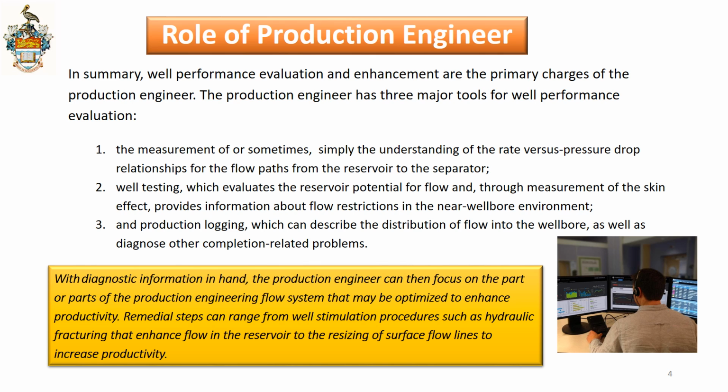Well testing evaluates the reservoir performance and also how the well is actually delivering the fluids from the bottom of the well to the surface, through basic well testing, which is routing a well to the test separator and measuring the rate and the flowing bottom hole pressure. Another technique would be production logging, running PLTs to determine what contribution is coming from which part of the reservoir itself.